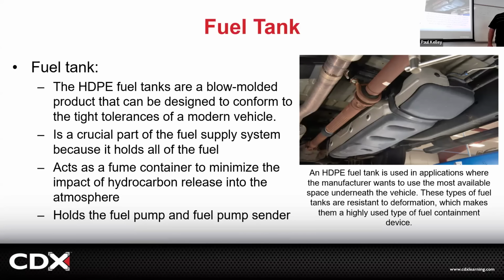But if you have a liquid fuel leak, it may not catch it. It doesn't really monitor the liquid fuel. It monitors the vapor pressure on top of the fuel in the top side of the tank. So if you've got a drip right here, you probably won't have a check engine light. That's true. But if you do have a vapor fuel hydrocarbon leak, that system, I'm going to bet you, is going to catch it, unless there's some weird malfunction, which would be a little strange.